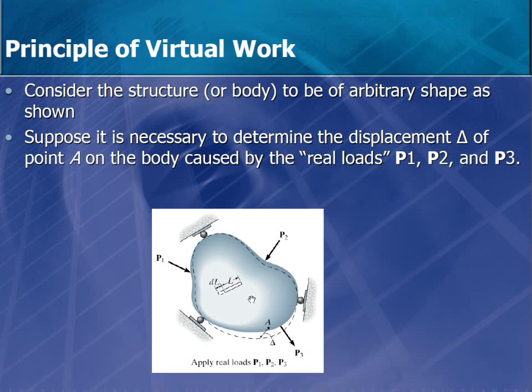Before going to the virtual work method, those loads we have here are affecting the body internally. An element within the body will be deformed by dL, because the load is going to deform the shape. We call this the real structure. The real structure creates delta L. Delta L is a real deformation due to the real load.